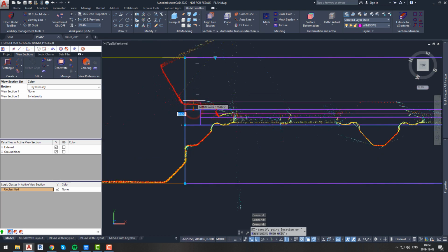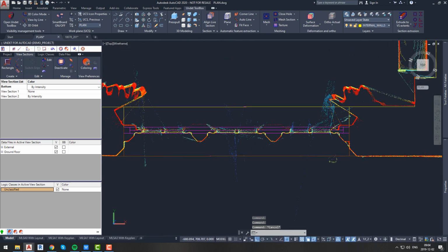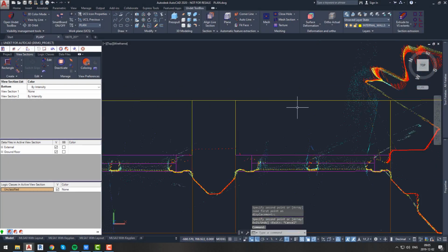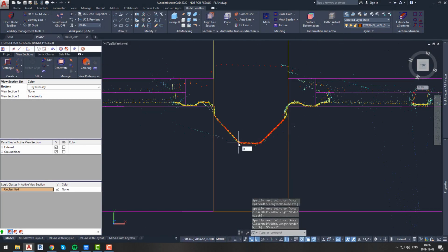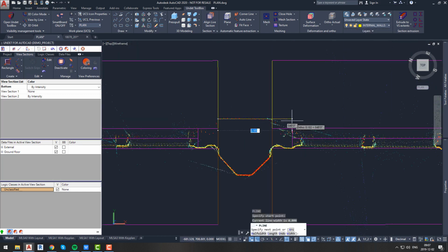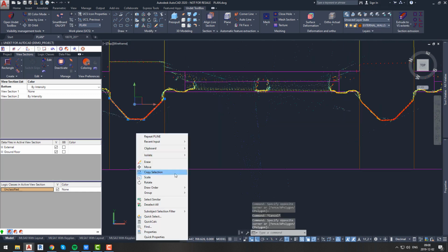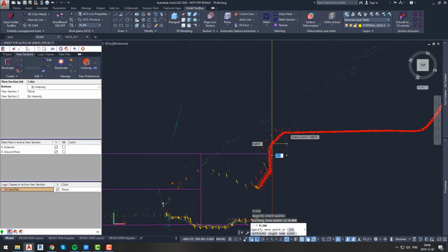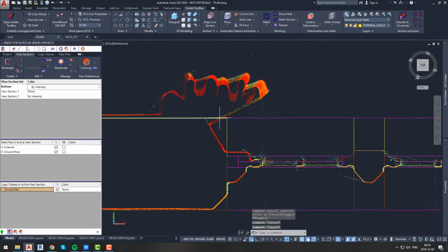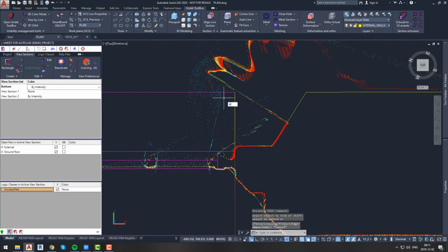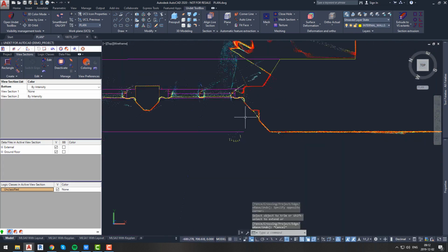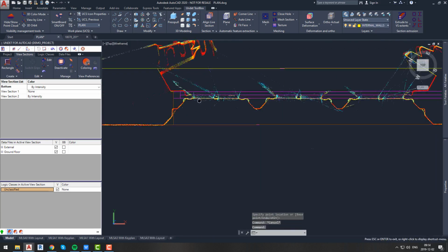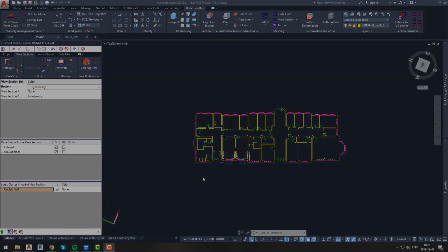Usually you can add one window block throughout the whole length, but in our case these windows are separated by a wall, so we will show them as 3 separate windows. With our window blocks you can easily change window size, length, profile size and so on. After adding and adjusting the window, we should apply them to the whole plan. Now we can see how our plan looks with doors and windows.